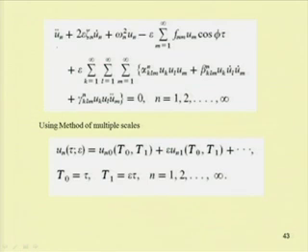So, in this case the temporal governing equation of motion is ∂²u_n/∂t² plus 2 epsilon zeta_n ∂u_n/∂t plus omega_n square u_n minus epsilon sum over m equal to 1 to infinity f_nm u_m cos phi t plus epsilon summation k equal to 1 to infinity, l equal to 1 to infinity and m equal to 1 to infinity alpha_klmn u_k u_l u_m plus beta_nklm u_k u_l dot u_m dot plus gamma_klm u_k u_l u_m double dot. So, due to the presence of this term, this is u_k u_l u_m.